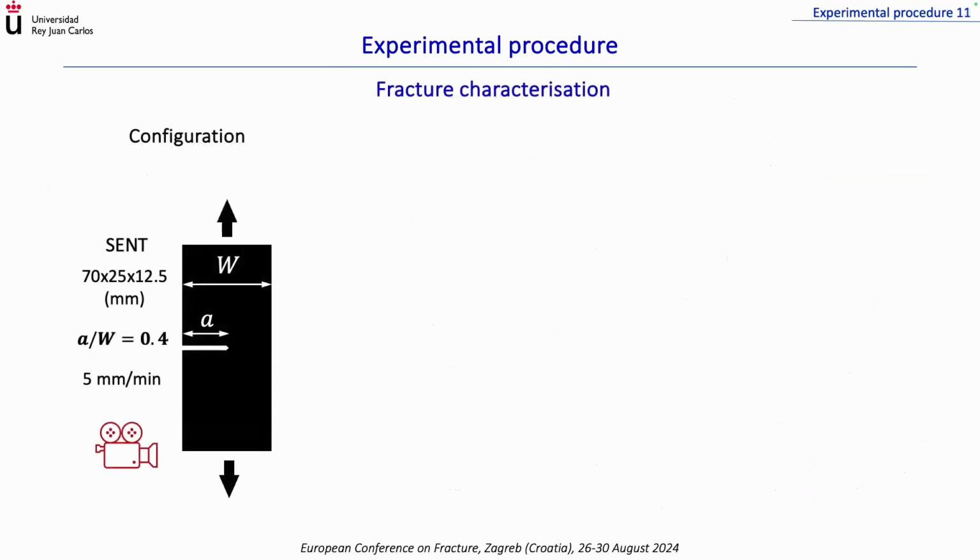For fracture characterization, we used single edge notch tension specimens. The sharpening of the crack was carried out by razor sliding, and all the tests were recorded because from the surface we measured the crack length evolution and also the crack tip opening displacement.